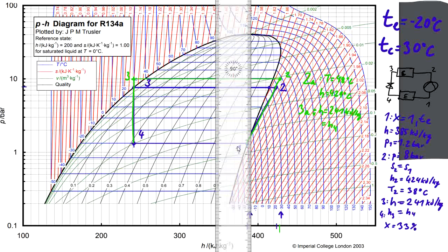So you can already see here that you have a higher difference in enthalpy for the compressor, while here you are basically at the same enthalpy. You have to end up with the same enthalpy difference 4:1, so this cycle would have a lower coefficient of performance, lower energy efficiency ratio of cooling. There, however, might be a reason why you would make a cycle like this, and this would be to allow the cooling fluid, let's say cooling air, to heat up in the heat exchanger.